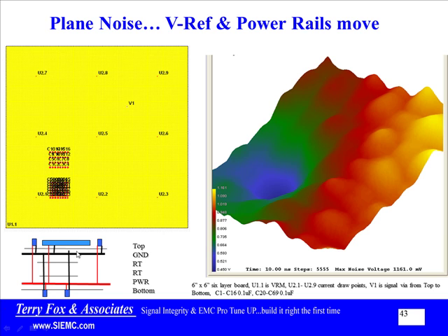So this is just a straw man setup that I put together, and here I've got 25 0402 0.1 microfarad capacitors, and this up here I think was 16 10 microfarad capacitors, and then the rest of this little example was just showing different places where I had vias, where I had power pins, and of course all of this was done with the HyperLynx LineSim.